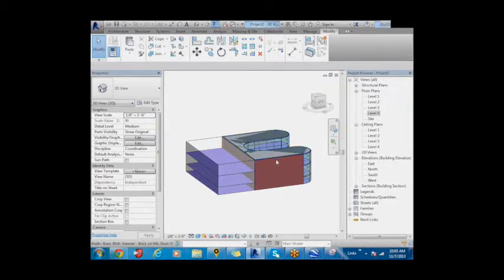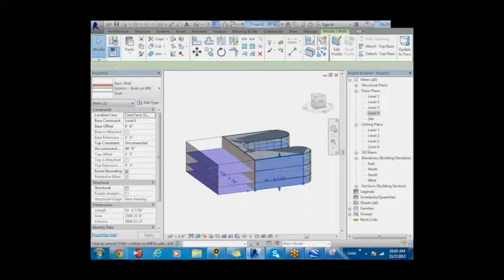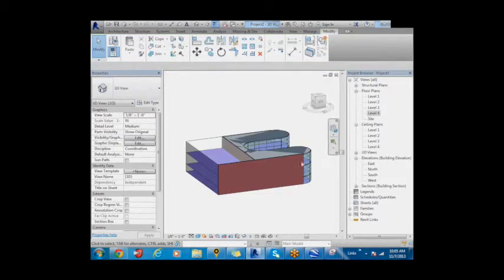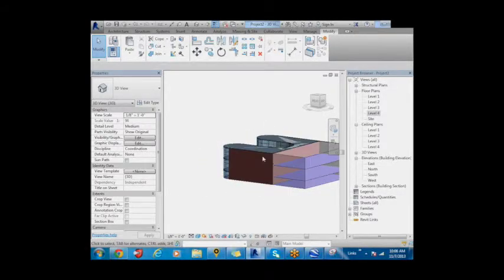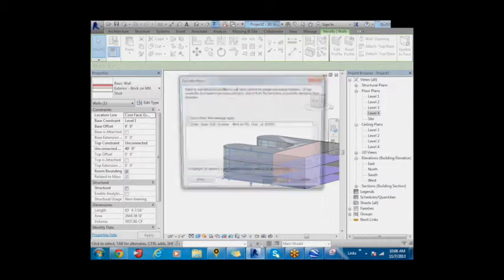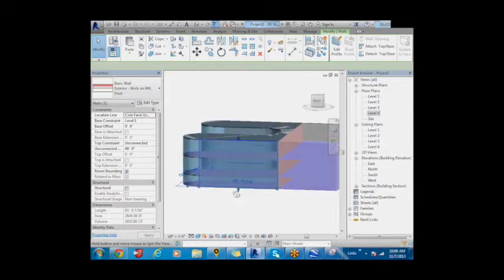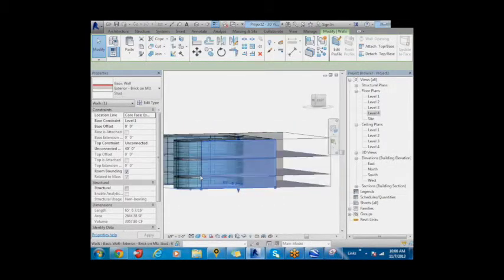All right. So we select a wall, and then we click on this button that says update to face. You can just press OK, and then the wall is extended to your new size of the conceptual mass. Similarly, we do it with the other face of the wall. Before that, I want to do that to my floors as well.